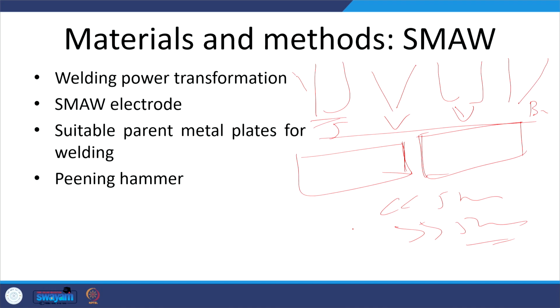When the thickness is more than 5, but say maybe around 10 mm, but if the thickness is further greater, then what we do, we go for the double edge preparations like double V like this, double U like this, and the double bevel or the double J in this manner.